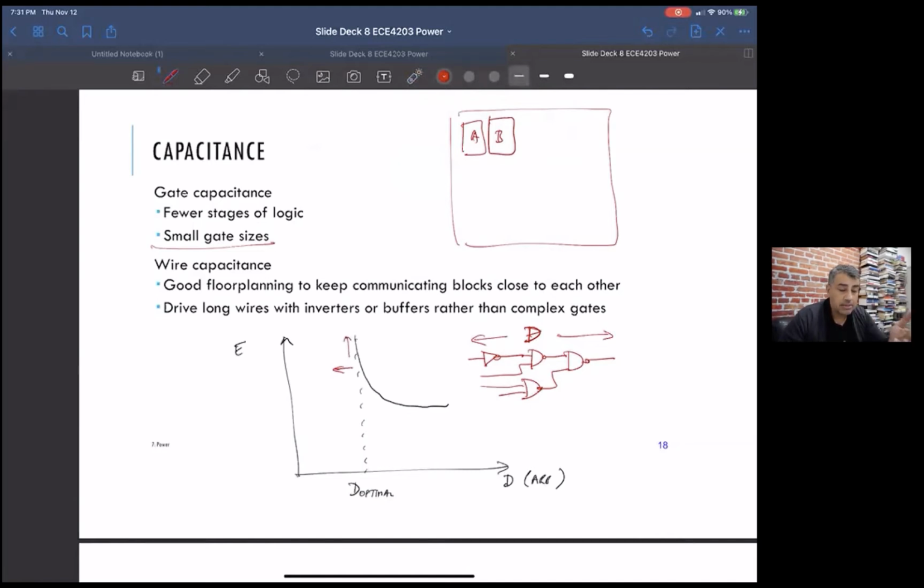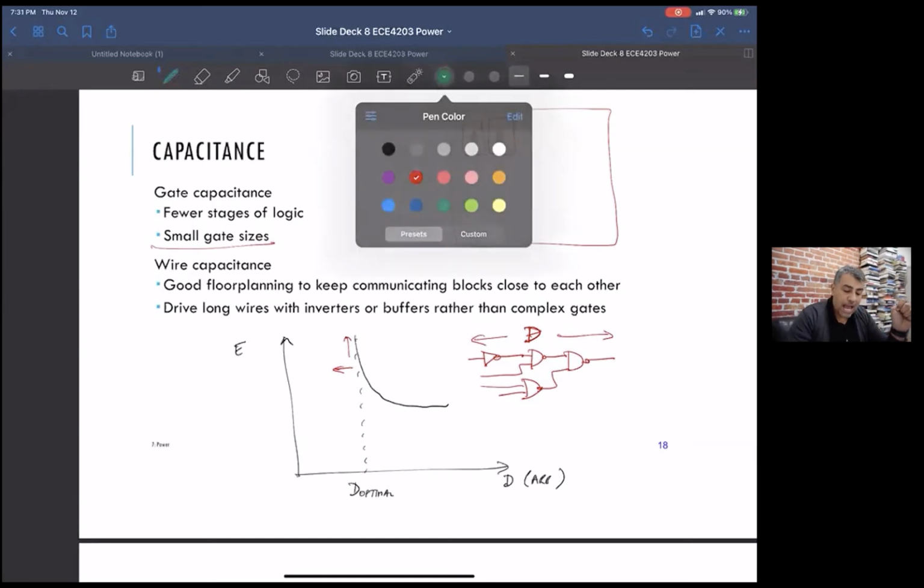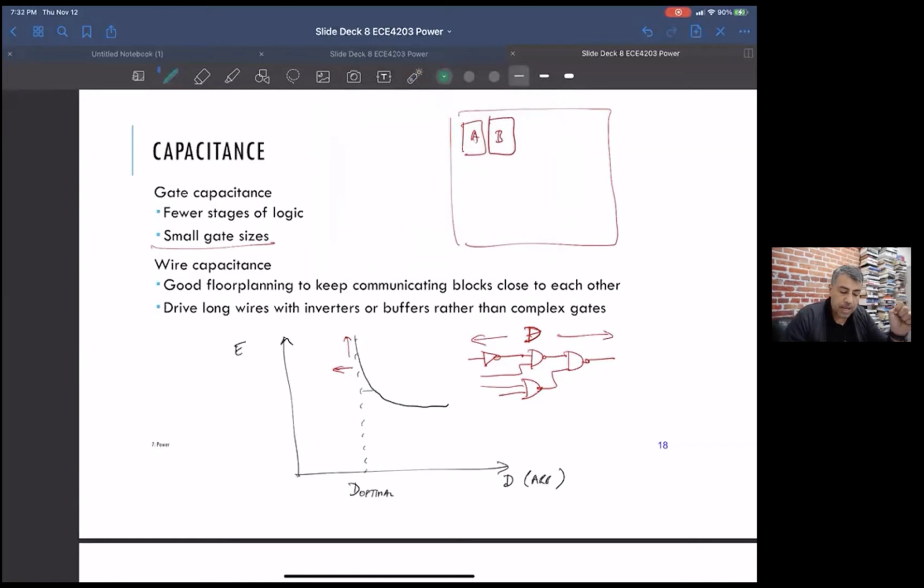We see this in digital design, and you see it in analog design. Once you try to push the speed too far, given a particular design implementation, your power just goes through the roof. Conversely, if you just back off the absolute minimum delay, your power goes significantly down. So you get a big, big improvement.